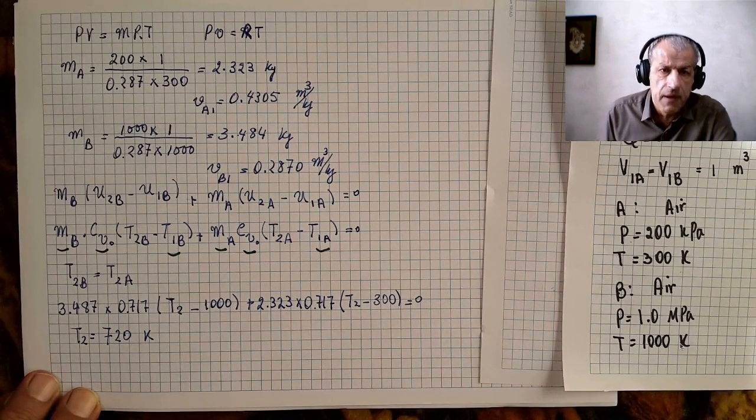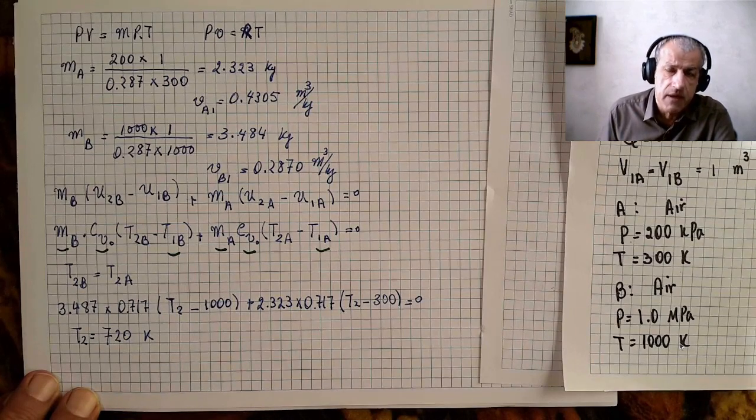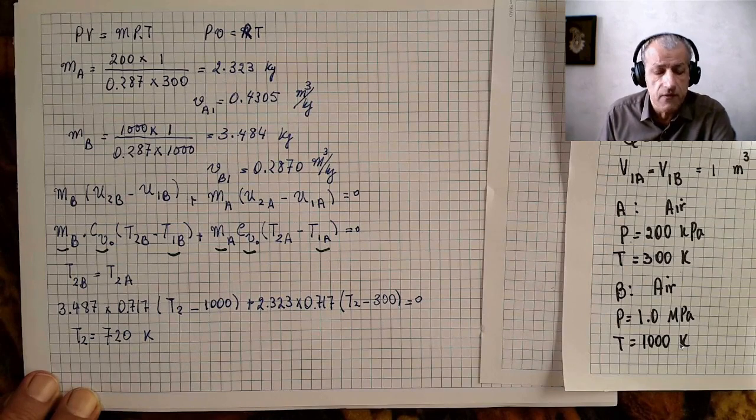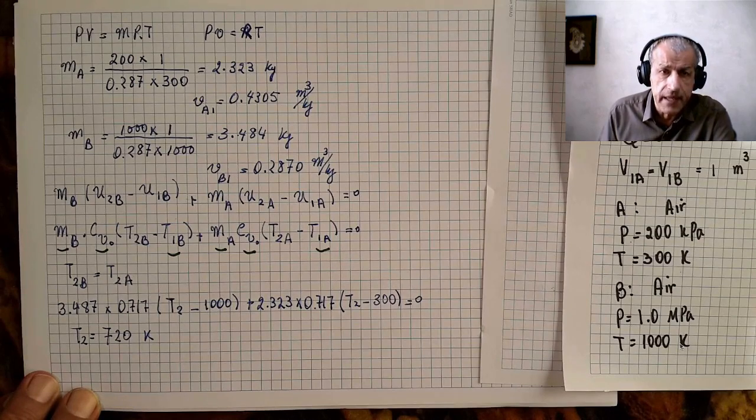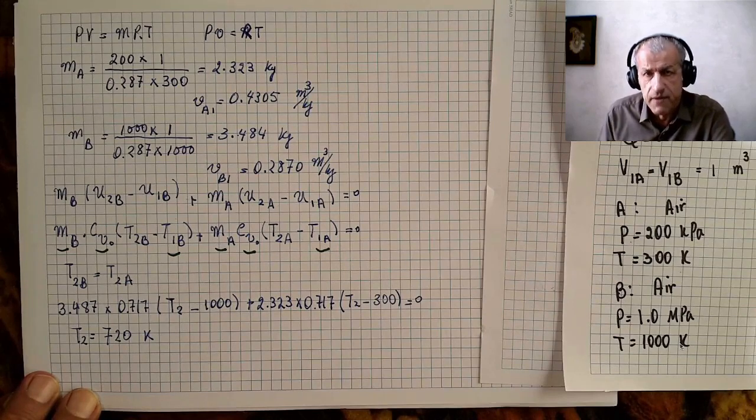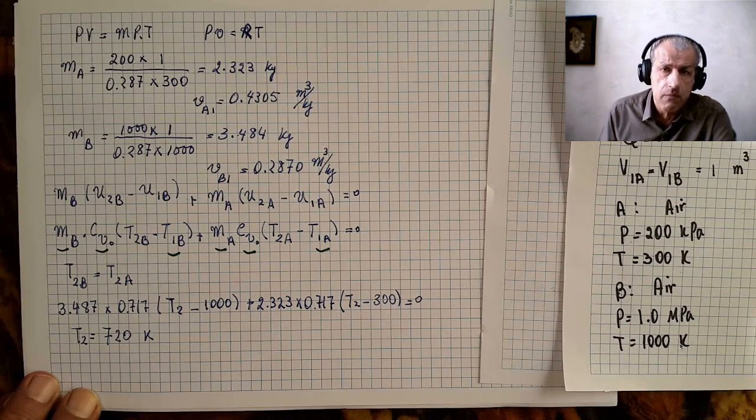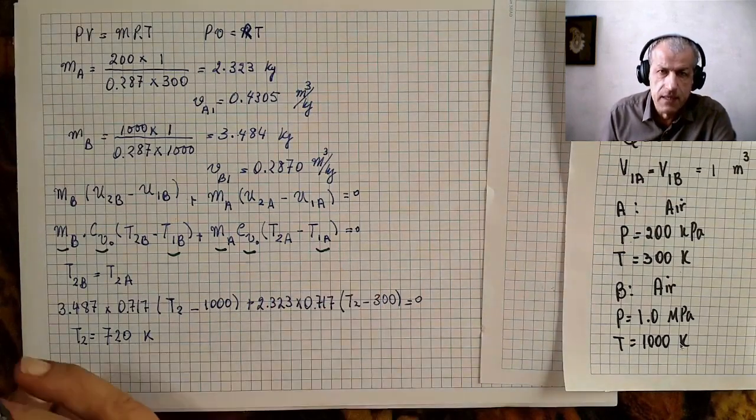The knowledge of the final temperature in both A and B could give us the final pressure and the final volume in both A and B. For this part, what I would do is just take them all as a whole, because in fact when the piston takes no pressure or no temperature difference, we could take A and B as the same cylinder.